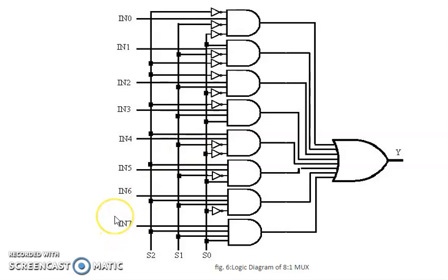Realization of a multiplexer is done using basic gates. Here is the circuit for an 8:1 multiplexer. We all know the expression, as we have already written the expression for the output Z, A bar I0 plus A I1. Here it is written for the 8:1. There are 3 select inputs, named S0, S1 and S2, where S2 is the most significant bit. The earlier example used A, B, C; now it is S2, S1 and S0. These are the inputs I0 to I7.